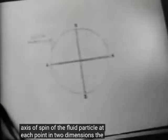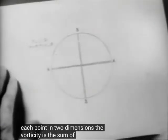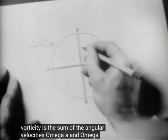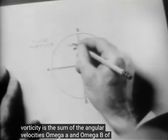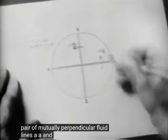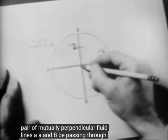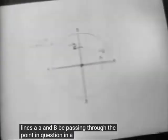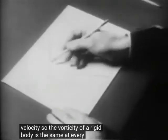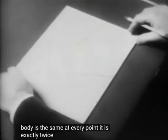In two dimensions, the vorticity is the sum of the angular velocities omega A and omega B of any pair of mutually perpendicular fluid lines AA and BB passing through the point in question. In a rigid body, every line has exactly the same angular velocity, so the vorticity of a rigid body is the same at every point.